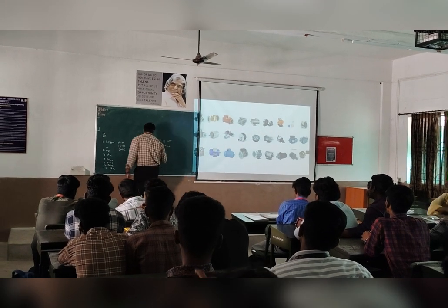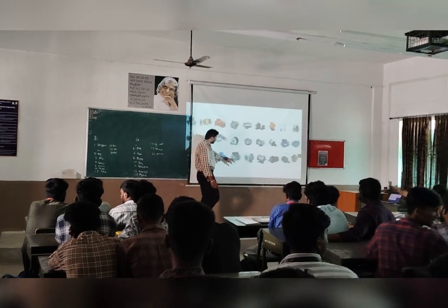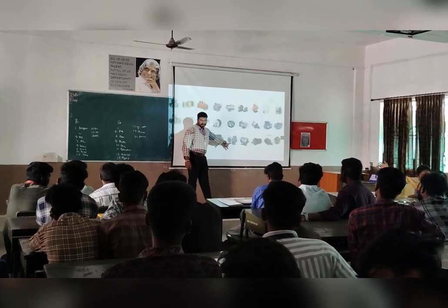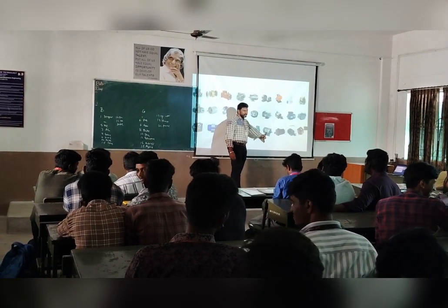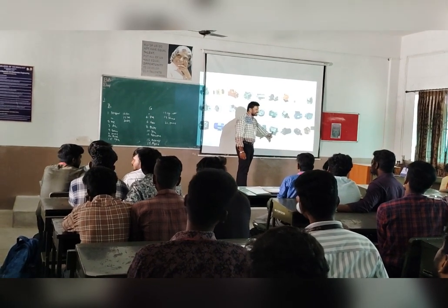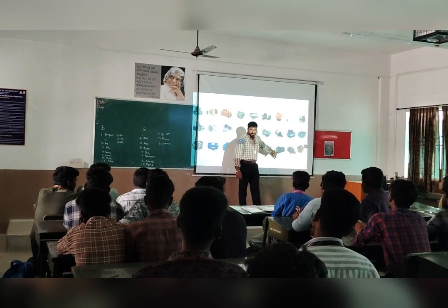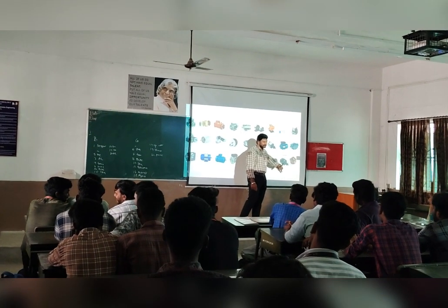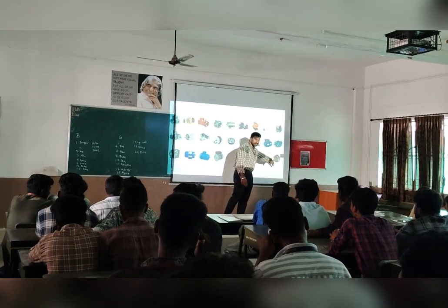So this will be spur gear. Just see the diagram. The tooth is parallel to the axis of rotation and they transmit power from one shaft to another parallel shaft. They are used in electric screwdrivers, oscillating sprinklers, wind-up alarm clocks, washing machines and clothes dryers. So that means we have two parallel shafts, and the power is transferred to the parallel shaft only, without any change in speed.